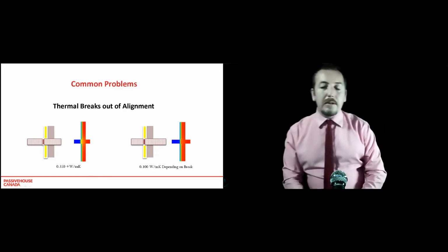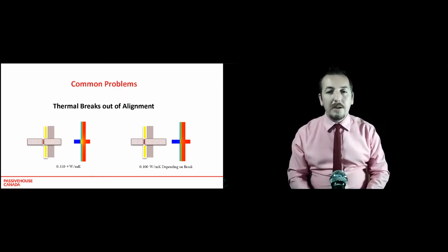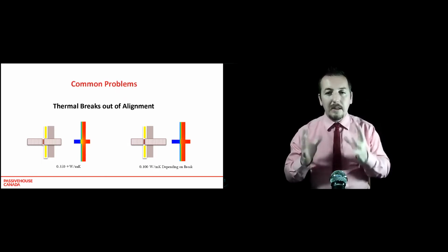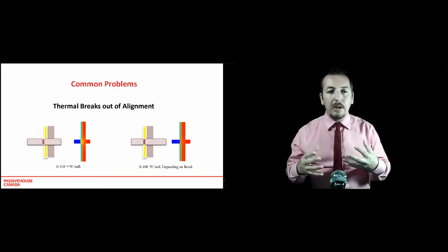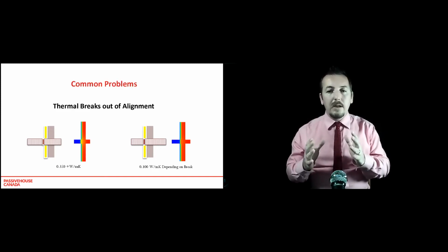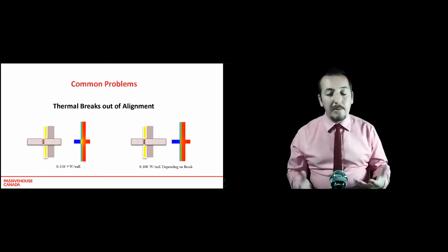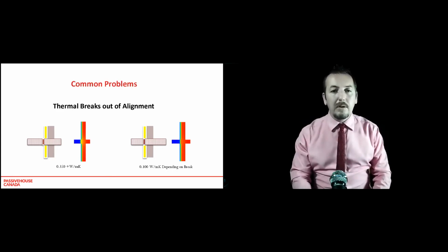And with thermal breaks, especially in this case with a balcony connection, it's very hard to get good values or thick thermal breaks and still be structurally viable. So if you're going to go through all that trouble, expense, and cost, and the thermal break is only as good as it can be, not putting it then in the insulation layer, you might think this sounds stupid, but it has happened so many times.